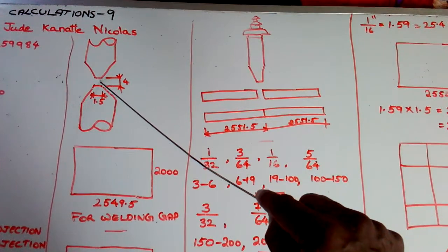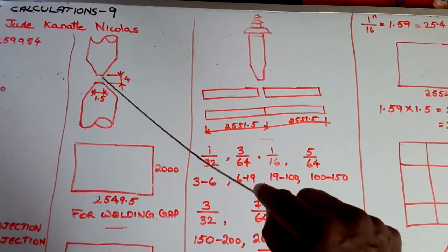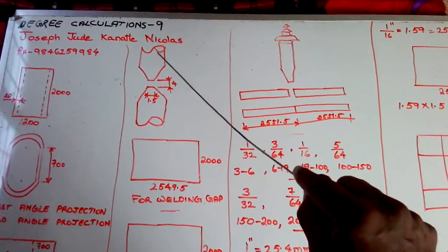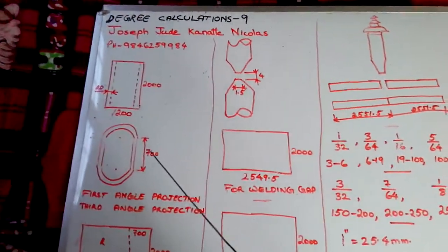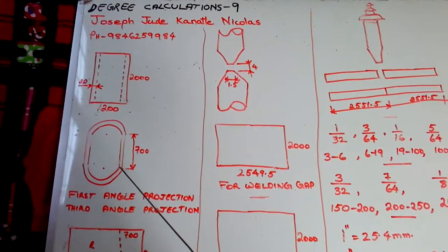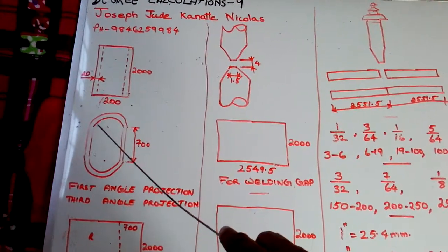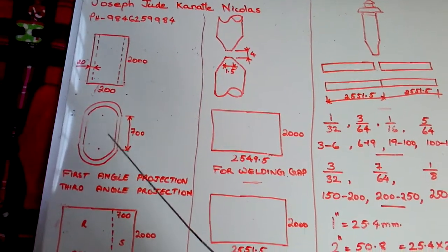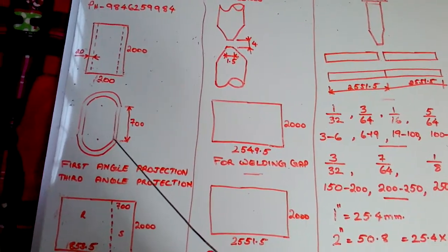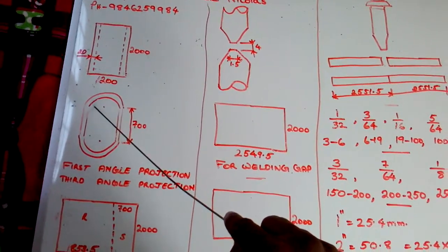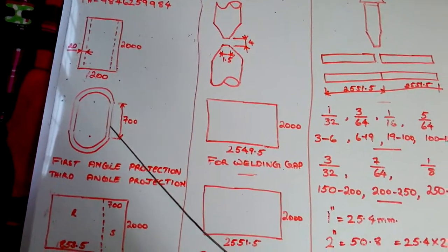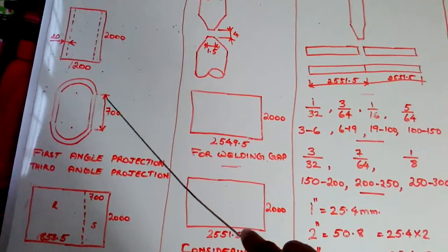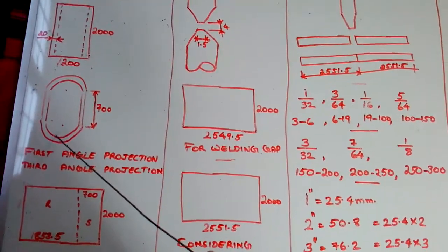From center to this much is 2 mm, then total 4 mm. It means for making this kind of job, in this portion and in this plate, I am indicating this plate, here we have to give a 2 mm gap, and here a 2 mm gap. Total 4 mm gap we have to give for this material, and the same 4 mm gap for this material also.